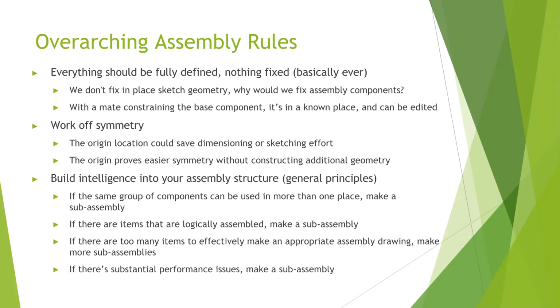So at the top level, if you have 10,000 mates versus 10 subassemblies with 1,000 mates each, and you make a change at the top level, SolidWorks is going to live calculate 10,000 mate solves. If you have 10 1,000-part assemblies at the top level, you only have 30 mates, and if you change a mate, you are only calculating 30 mates. And if you open up one of those subassemblies with 1,000 mates and make a change, you're calculating 1,000 mates, never 10,000 at one time.